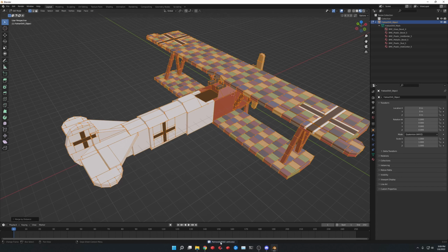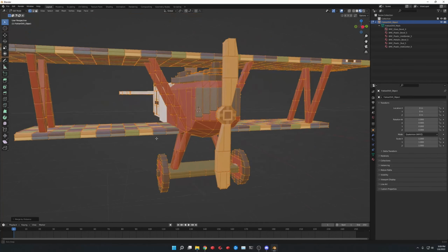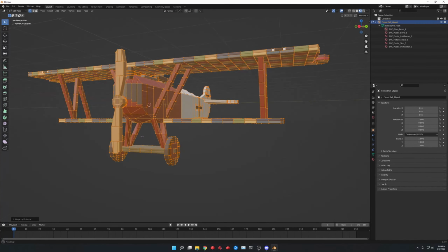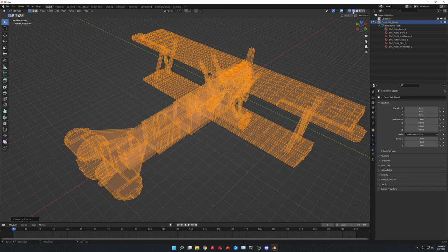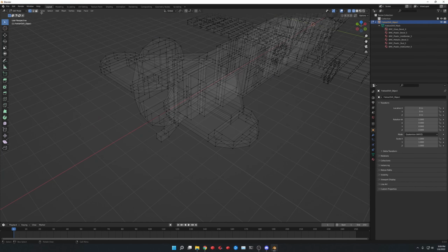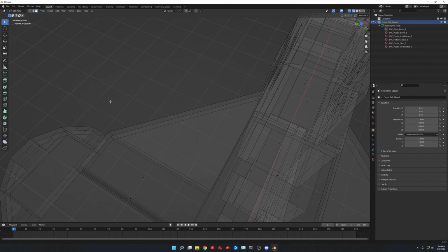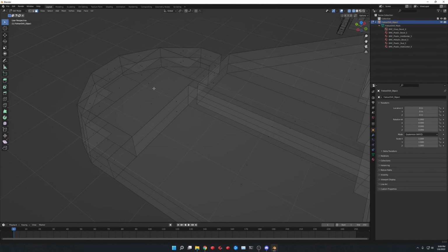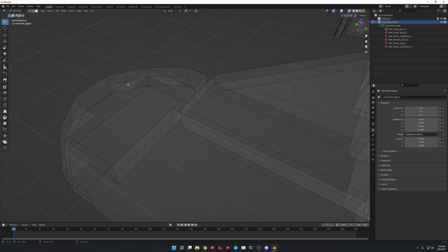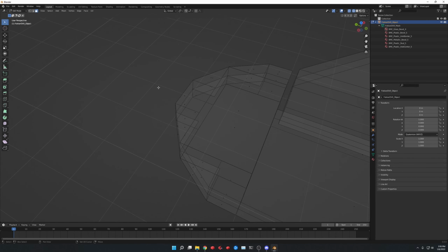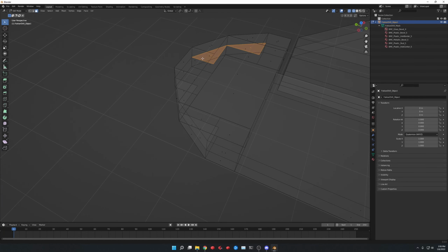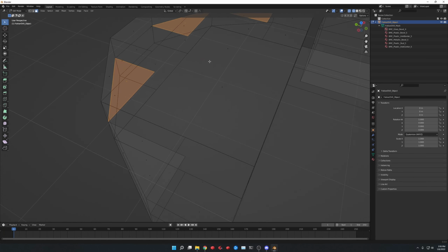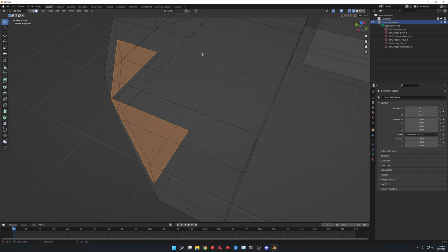And as you can see, that removed 8,560 vertices, so that'll make the model a little easier to work with. One thing we can also see if we go into the wireframe mode and look at the faces, you'll see that even though we exported it without the internal faces, there are still some leftover internal faces. For example, these little triangles in here. And these can be annoying when trying to create the vertex groups for the rudder control, elevator control.